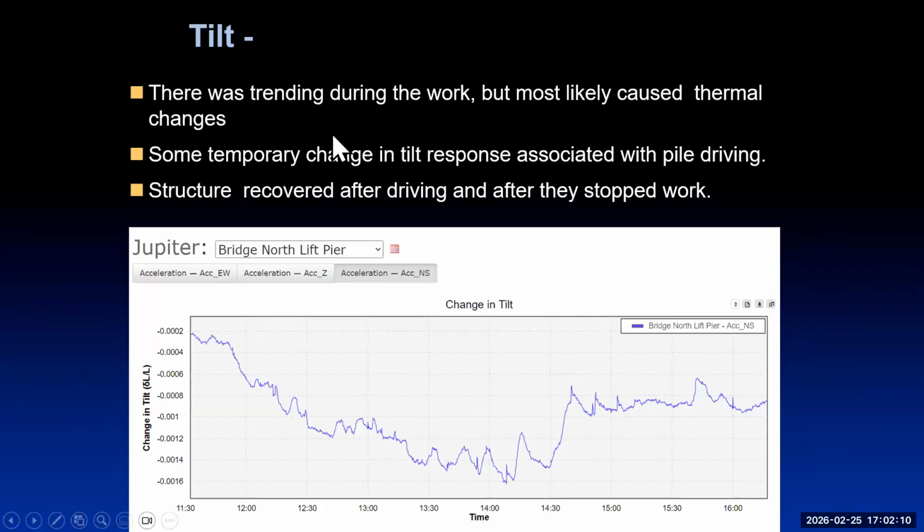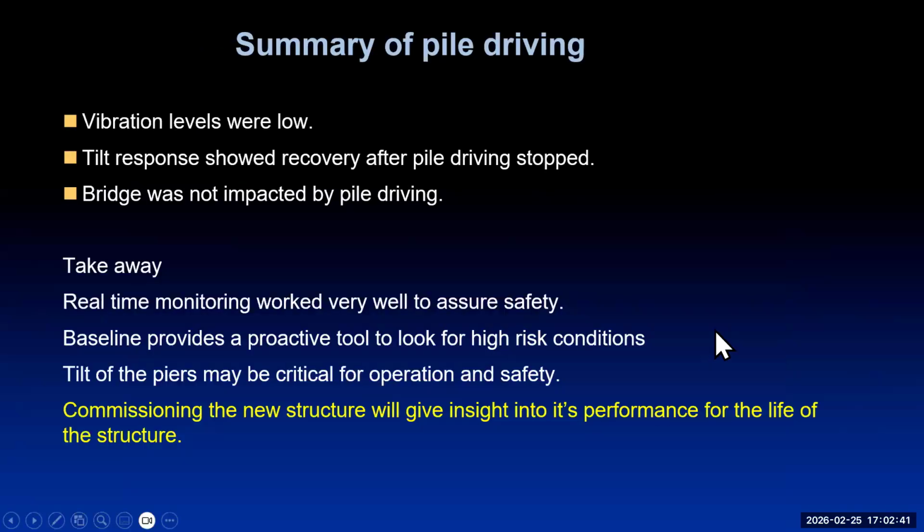And then during the process of impact, the structure will respond and the soils will respond, and you'll get a tilt response and you'll get some recovery from it. So it's actually a very interesting phenomenon. And when you're measuring down to about 1/10,000th of a degree of movement, you can actually see this in real time and see the recovery of the structure. And then you can understand if pile driving is actually causing settlement and displacement and things like that. So you get real-time feedback with that.